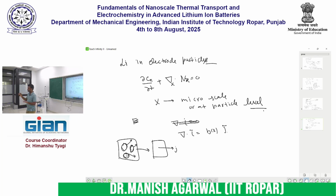I want a fairly approximate result, and that is fine with me. So I will calculate the total heat that is generated, let's say Q. Then I divide this by the total volume of the domain, and use it as a heat source.